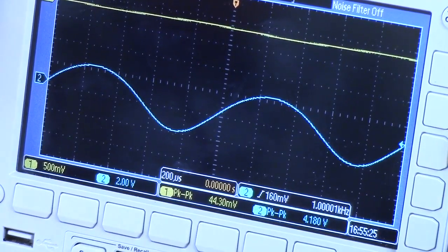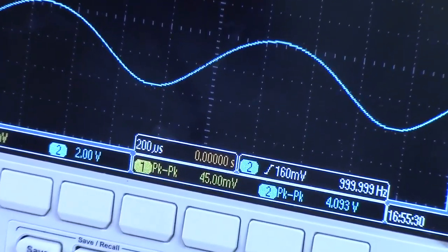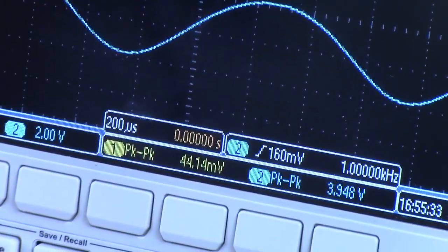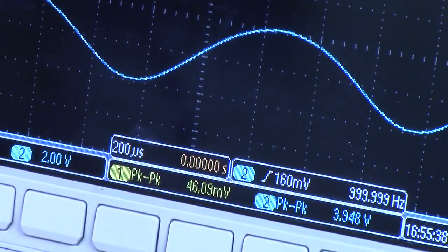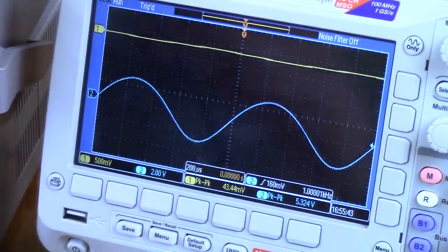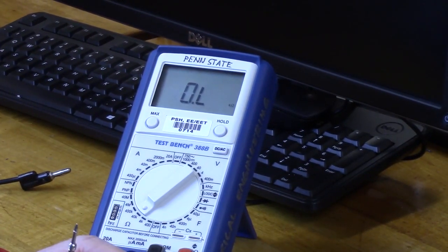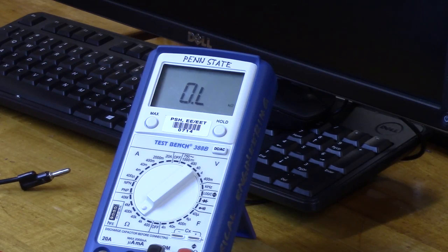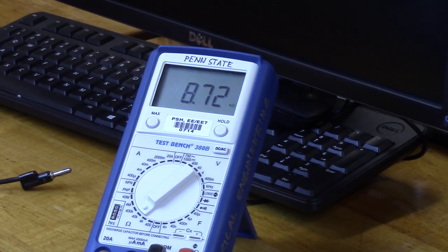It's just a hair above. So let's tweak that until we get to about like that. Okay, so right now our pot is dividing our input signal in half. So bypassed, our output impedance is going to be, the envelope please, 8.73K. So it's very similar to what it was bypassed versus unbypassed. Output impedance really does not change very much.